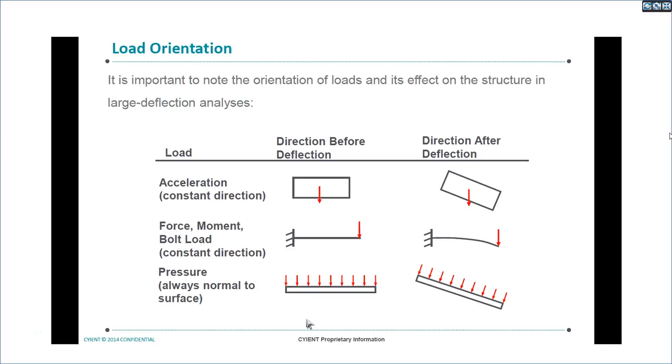Okay. So when you try to apply pressure, pressure always acts normal to the surface. So this will give perfect results. If you want to apply load always normal to the surface, it is always advised to apply pressure instead of point loads. Okay, so point loads will be acting along constant directions. So it is very important for us to understand how to apply loads. Whether it is a nonlinear geometry will have a significant role in load application.